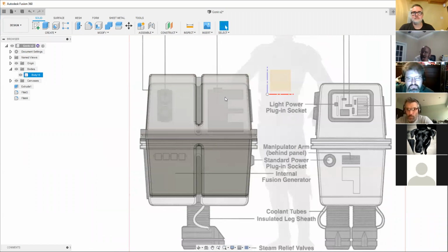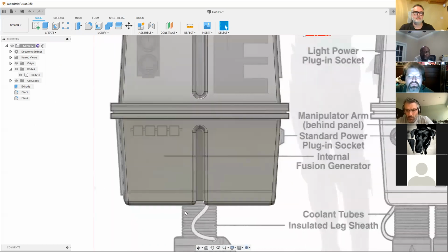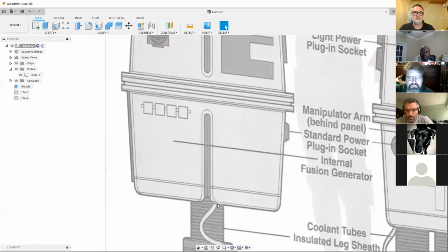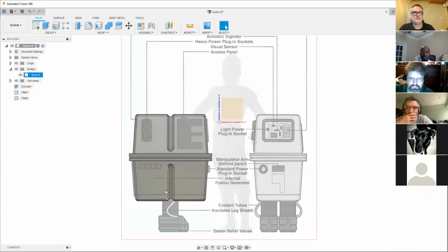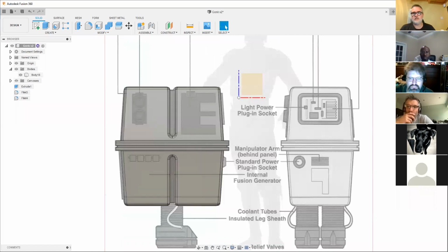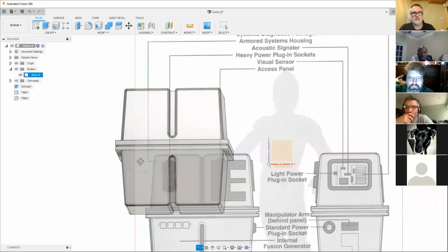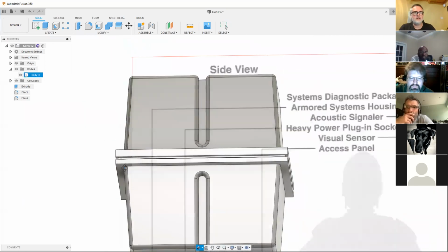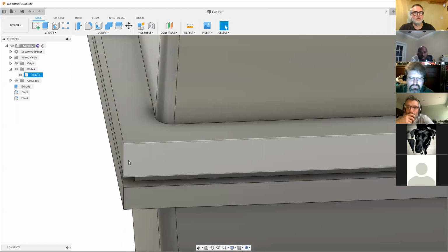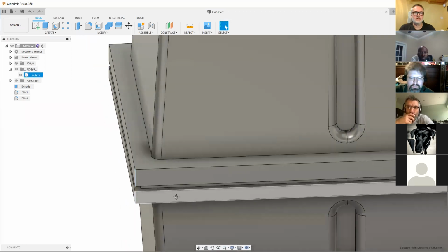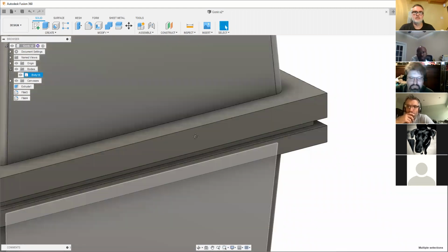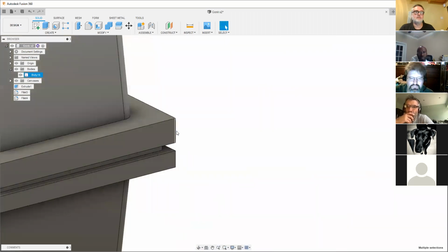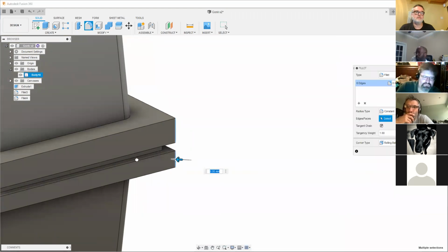So let me ask you one question. Say, for instance, at the bottom of the curve, if you wanted it less rounded, would you do those fillets separately, and maybe instead of 3, use a 2.5 or something like that, if that's what your design was? Yes, you can do fillets independently, absolutely. So what we'll probably do is put some fillets on these corners as well. Again, we just highlight the corners, but we might want a slightly different fillet on those. Gotcha. I was just wondering because I'm trying to think ahead to something else I might do in the future. All right, thanks.